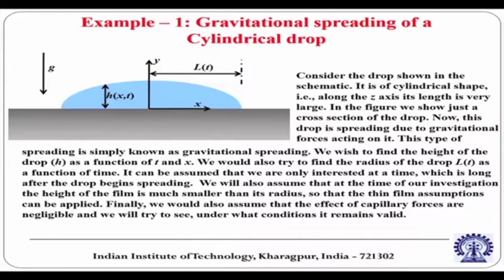Why? Because initially when the drop starts spreading, the inertia force may be important. In the thin film analysis that we have made, remember that you can make thin film analysis even with inclusion of inertia force, but the special type of thin film analysis that we have made, the traditional, classical thin film analysis, by utilizing the ratio of the length scales, we have trivially neglected the inertial forces.